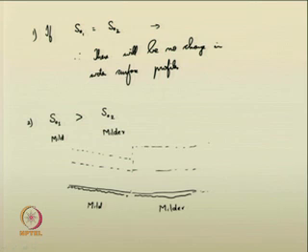So, theoretically this will be the normal depth for channel 2, and this will be the critical depth for channel 2. The critical depth for both the channels is the same. So, this is y n 1 and this is y n 2. In a steady situation for uniform conditions, the flow has to reach the normal depth.